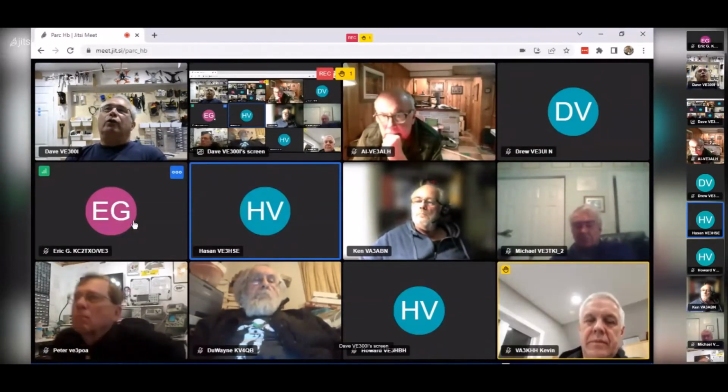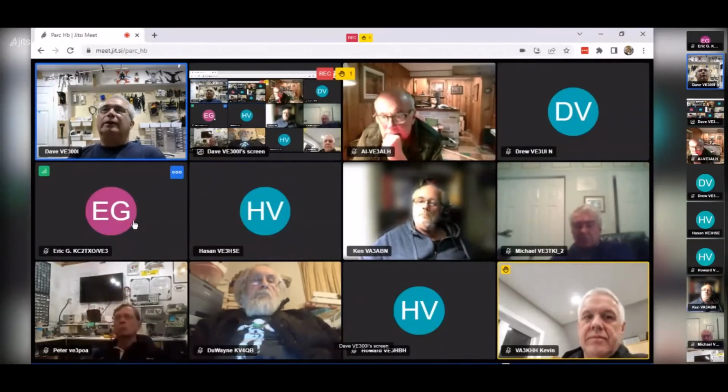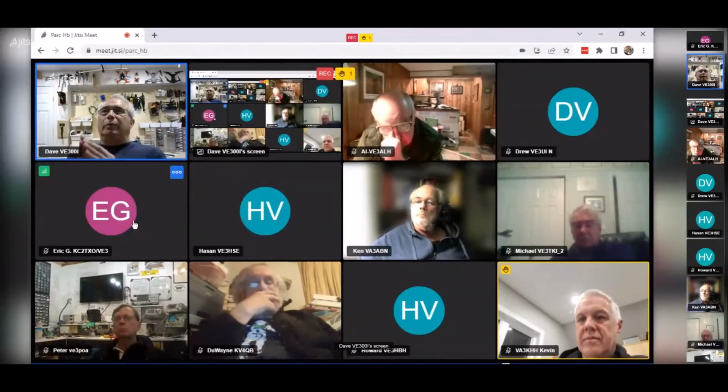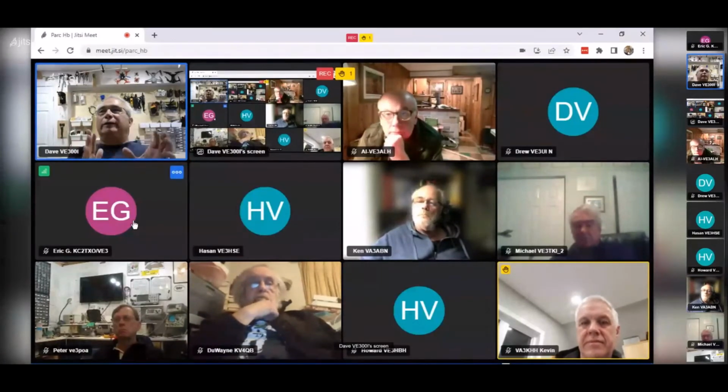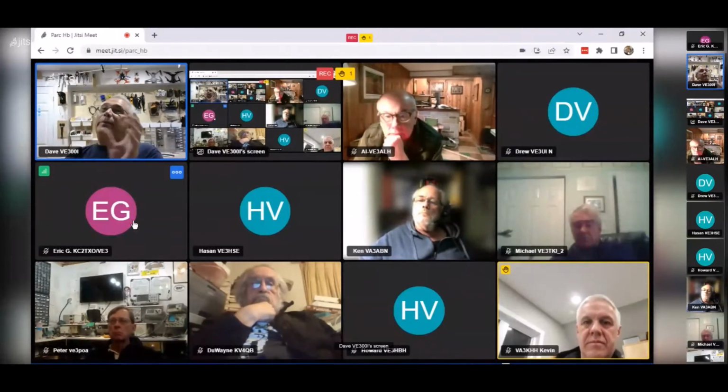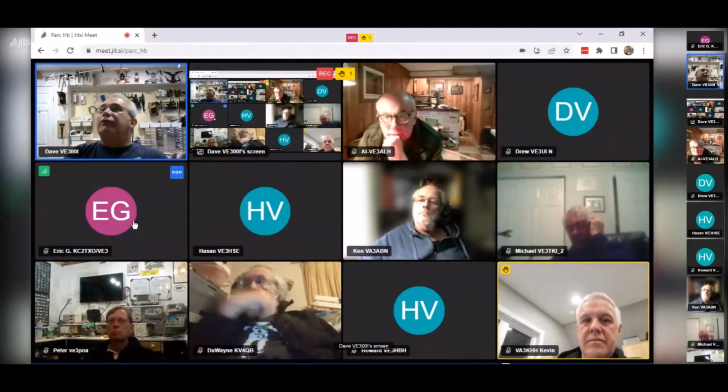And also keep in mind, Hassan, that with your PID, you're measuring error and multiplying it and getting an output. The bigger the error, the bigger the output, so the more you have to move. So you've got a bigger PID number, which equates to a smaller pulse width, because the faster the pulse rate is, the faster the motor turns.